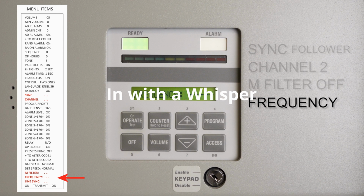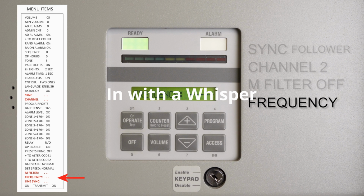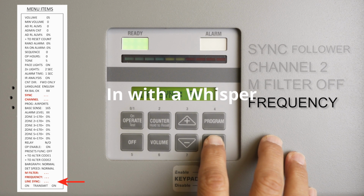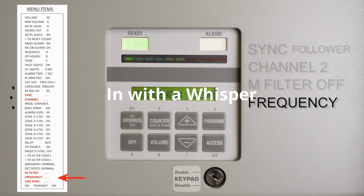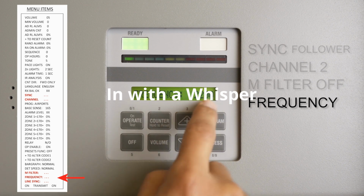Notice frequency is set to all dash lines. In order to enable this menu item, line sync must be modified. Use the Access button to scroll down, modify line sync to off. Use the Program button to scroll back up to frequency. And notice the menu item has been enabled and the frequency is shown above.